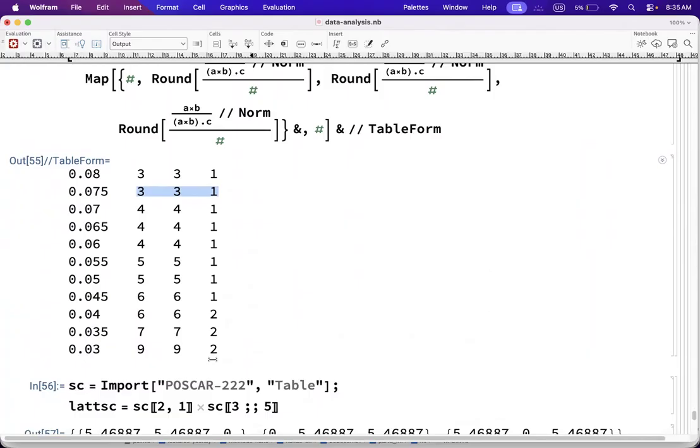But since we're going to use machine learning, we have to use the same equivalent grid we used for the machine learning, the one in 7 7 9. It's equivalent to 2 by 2 by 2 in the supercell of 2 by 2 by 2. And here it will be 3 3 1. So that is the grid we have to use if we want to use machine learning. Okay, so just to repeat again before I do the calculation: you have to be careful with the grids, right?